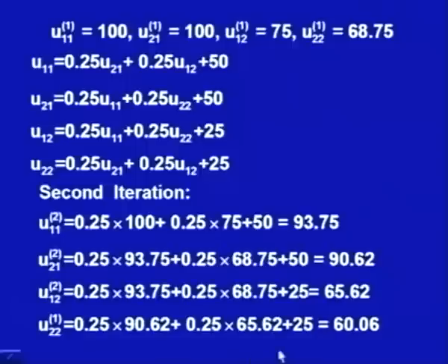So, this is our Liebmann method, which tells how to find these solutions. We already know that my actual solution is 62.5, 68.5 and 82.5. This problem is a little bit simpler one, and you already know how to solve it. So, we can check it using the actual Fourier series, that is, the Fourier method, find out what the solution is, and check how near we are reaching to it. We can improve upon this convergence, or reaching the final solution, if we take a better guess. Normally, the guess starts from the boundary conditions, and we normally take this better guess. So, you can take this guess.